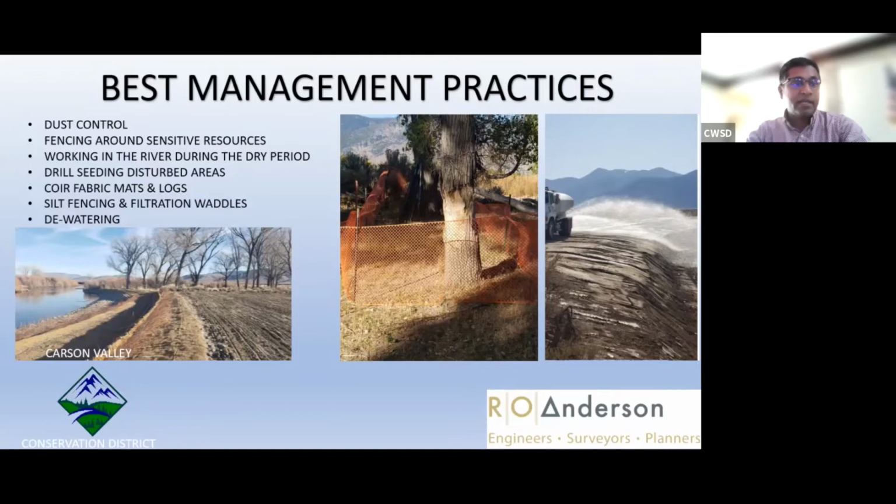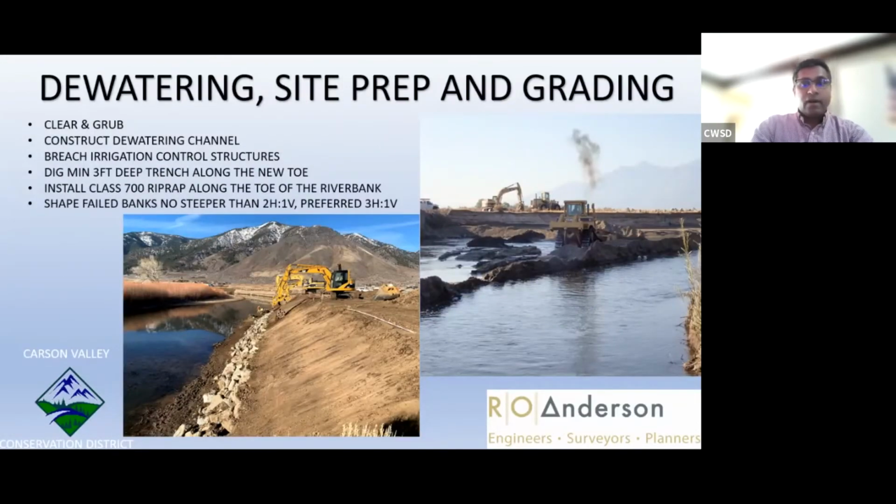A lot of silt fencing, as you can imagine, dewatering, like I said. Oh, other way around, sorry. So clear and broad, and the slide to the right, you'll see it looks messy. Yeah, we still have a lot of water in the river when we're working. But once you put in this dewatering channel, then for the most part, close to the river banks where we're working, it was at least relatively dry, I would say. The construction crew was able to go there and do the work without dropping a lot of sediment in the river, which goes downstream. It's not a good thing for anyone.